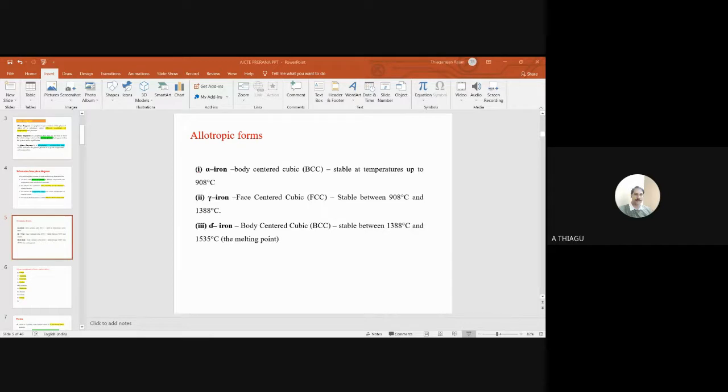So pearlite means a mixture of ferrite and cementite. But here we have to see some proeutectoid alpha and eutectoid alpha. Can you see the thing? So some formation of eutectoid structures is developed along with the pearlite. So proeutectoid and eutectoid formation is developed.